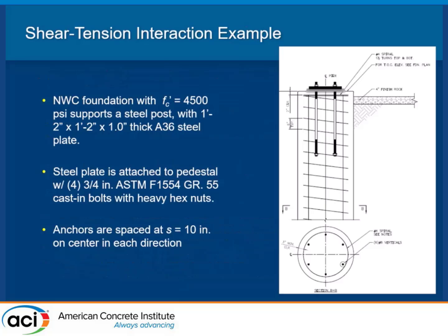As you started to say in the very beginning, this is a good example: we have a plate on top of a pier here, and I could say, okay, I'm going to jump right in and start checking all my modes of failure. Right away I look at it, and I already have some longitudinal steel. I know I have supplementary reinforcement. I know that I have these things deep in the ground for whatever reason. If you have a basic design pattern in your firm, remember H effective is going to have to go way up here. Do I even bother